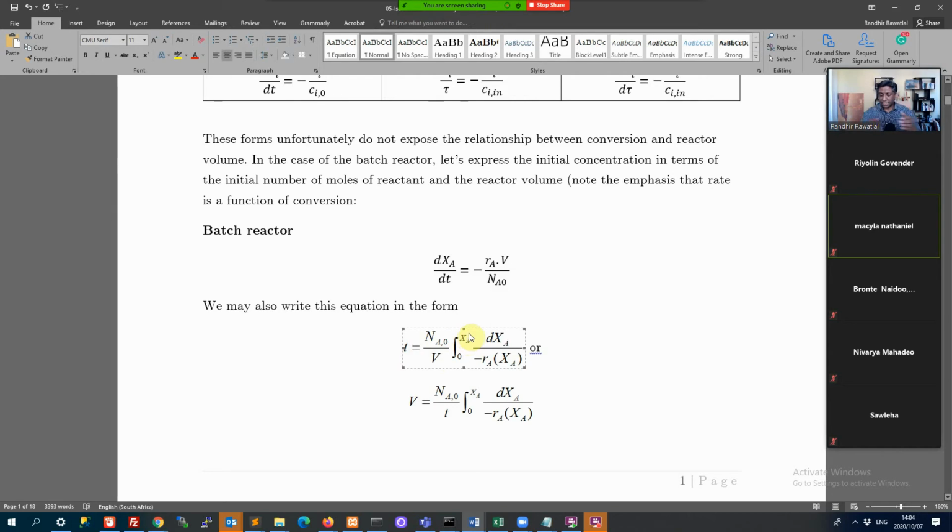Remember, it's a batch reactor. We start out with zero conversion and go through all the conversions, so by picking a final conversion, that tells us how long to leave the material reacting in that space. That's the time needed to accomplish that conversion.